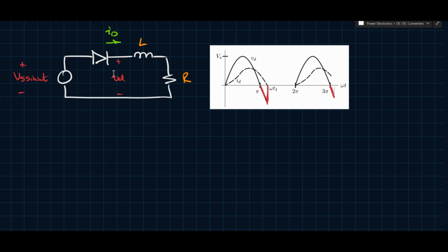If it doesn't, then what would happen is that if this diode's always on, then VD ends up being equal to Vs sine omega t, meaning that this average has to be 0, because the average of a sine wave is 0, right? But VD's average being 0 means there will be no current flowing here, right? So if VD's average is 0, that means this resistor's voltage average is 0, meaning the current that would flow through here would also be 0, right?